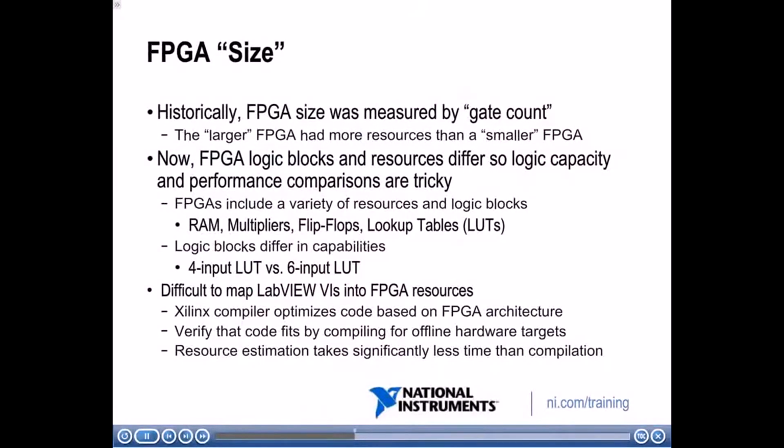Here we discuss FPGA size. So historically, FPGA size was measured by gate count. So here you would just say, well, whichever FPGA has the bigger gate count, that's the one with more resources and that has higher performance. However, now FPGA logic blocks and resources differ, so logic capacity and performance comparisons are tricky.